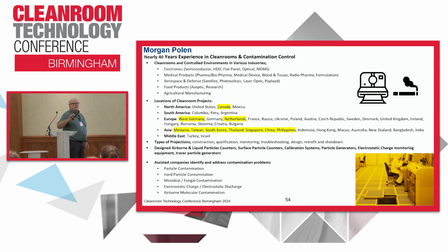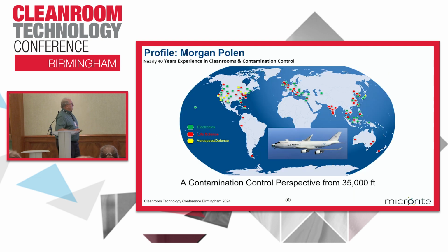The thing I learned there that was really important in contamination control is that particle size matters. Those of you in pharmaceutical manufacturing, has anybody ever come across an issue where you pass at 0.5 and fail at 5 micron when you didn't before? Chances are something is broken. And the same is true with smoke studies. When it comes to airflow visualization, particle size matters. And we'll talk a little bit more about that.